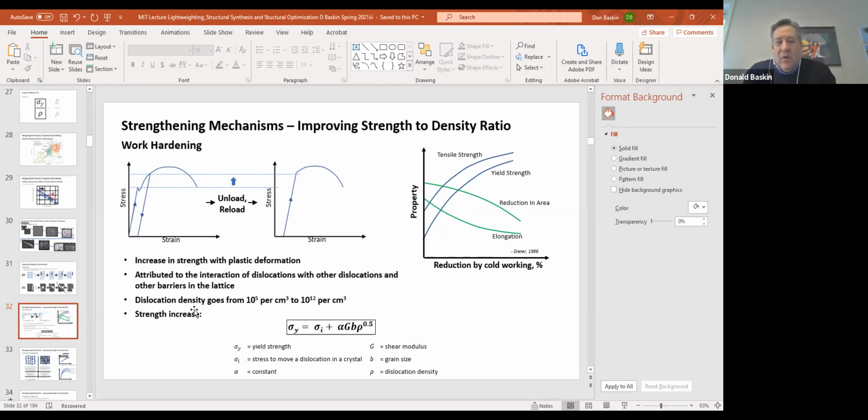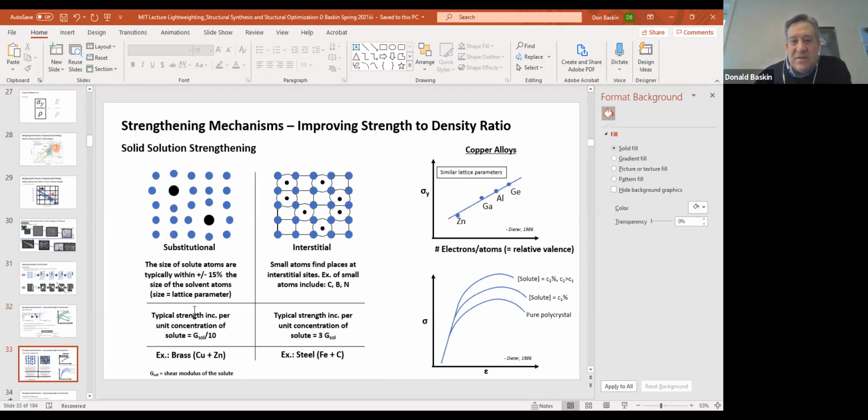Last time I think we talked about work hardening. This is a method by which you have thousands of kilometers of dislocation line, and you tangle them up with one another, and you make it really, really difficult, really high energy, to move these dislocation lines through the material. And that increases the strength in the bulk or the far field when you have a completed material, not just a bunch of atoms. I think this is the last slide we discussed last time.